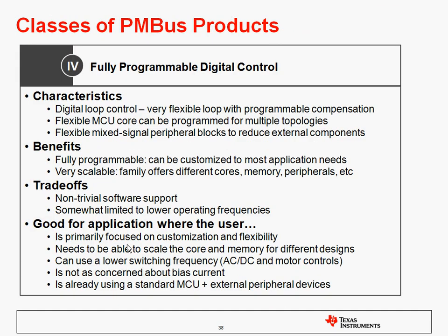And then the fourth and final class of PMBus product is a fully programmable digital control engine. So again, this is going to be the ultimate in flexibility and programmability. It's going to have a full controller core. It can be used in any topology, and the one difference is this is going to be more of a mixed signal microcontroller looking device that has a lot of different peripheral blocks, so that it can be used both in traditional power management applications as well as more system-oriented applications that also need some power management.